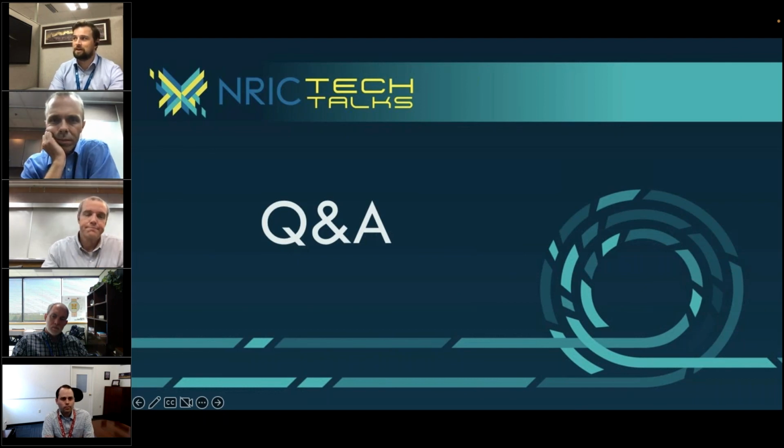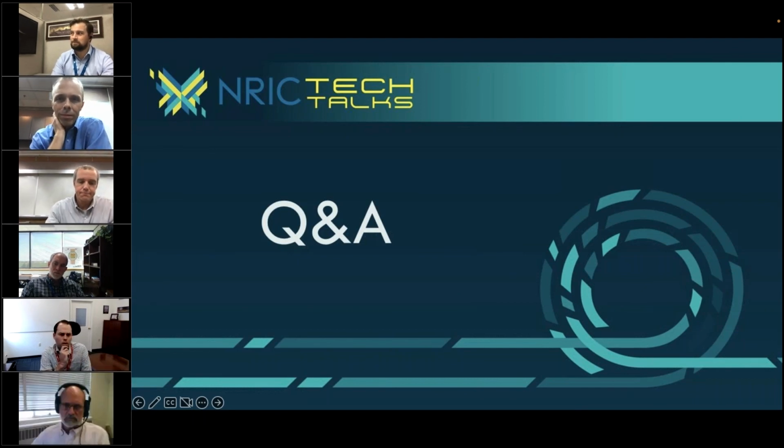Chris, would there be any change to HFIR and the materials that would be restricted at all? Yeah, I think everything that Nick and Colby said generally applies. I'll just add a little bit and say that mercury, I know, is not even allowed in the building because it can attack aluminum. And things like copper generally have to be doubly contained. Things that might attack aluminum if they get into the coolant, it certainly can't be exposed to the coolant.